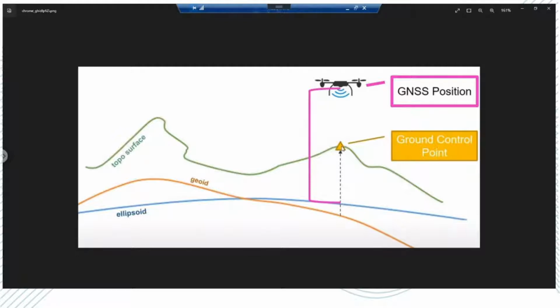There's something that I like to highlight: whenever you import your data in Correlator, this gets us to our very well-known coordinate reference system, which is WGS84, which is just contextualizing a point on a 3D surface, which in this case is Earth, and that's where we get our latitude and longitude. So when you're importing all your images into Correlator 3D, they're defaulted to lat and long WGS84. And I believe the ellipsoid height we're using is in meters. This is standard whenever you drag and drop, or import, your images in Correlator.